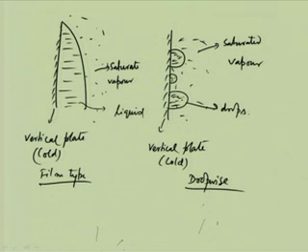As the vapor comes into contact, it goes on condensing and then liquid will flow like a film over this surface and gradually come down, so more and more molecules come to the bottom, and therefore that thickness will gradually increase. This is the film thickness. If I say this is x, then delta is a function of x. So we can expect that there will be a resistance of the film.